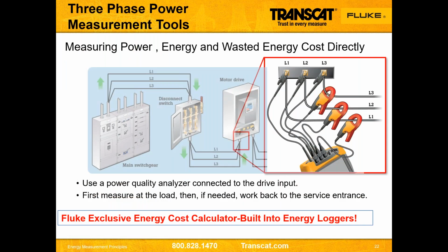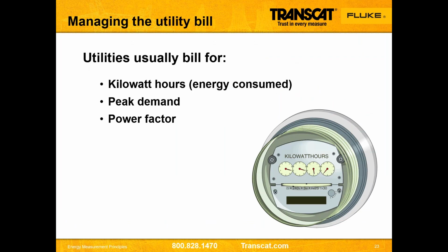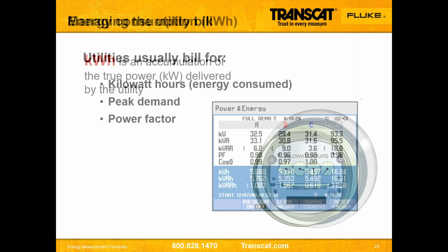So a 3-phase power analyzer is one of those tools. We kind of talked about that. And this is, again, I would be hooking up right at the main switch gear and then working my way downstream to go measure individual loads to see where the inefficiencies lie. We're going to look at all the 3 phases of voltages and all 3 phases of currents simultaneously, so that we can actually figure out and take a look at the power consumption piece.